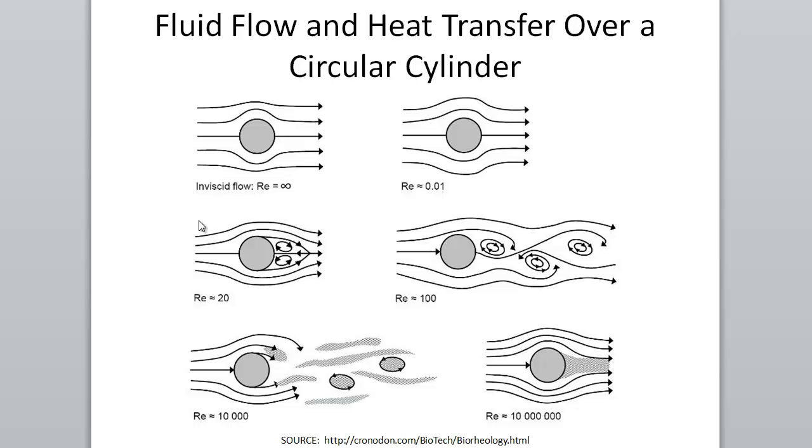We're going to focus on this laminar symmetric case, at a Reynolds number of about 26, I believe, in this analysis. But you can see we have symmetric flow about a center line here, and the flow separates and circulates immediately behind the cylinder in the wake. We're going to try to model this using ANSYS CFX.